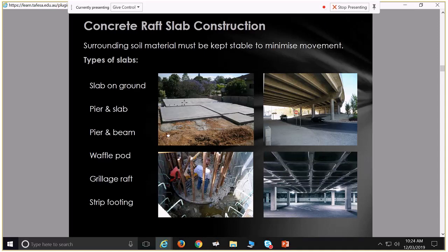But there are so many instances of areas being filled from various different things, or having, as Lee mentioned earlier, pockets where you've got sand and then clay, etc. So for those sandy sections that don't have much bearing capacity, you might need to bypass those. So you create your piers by using an auger that digs out a cylindrical section of soil, and then you drop in reinforcing cages like this. This one's a square one, but you drop in cylindrical ones into there, so our reinforcing, and then fill that up with concrete.